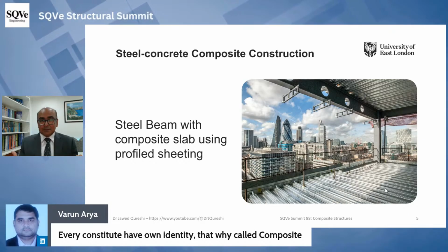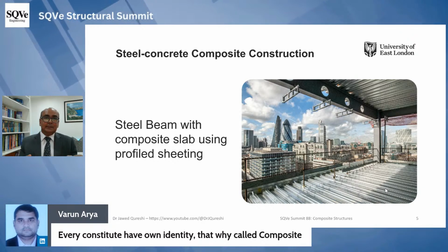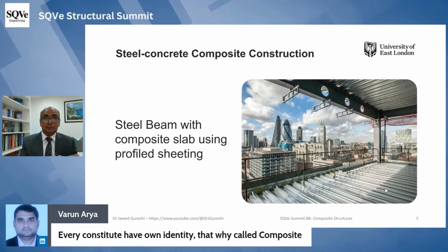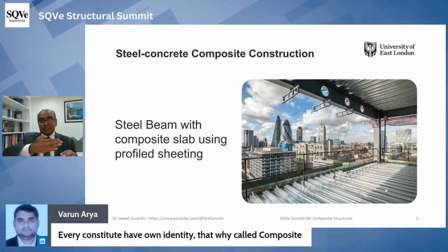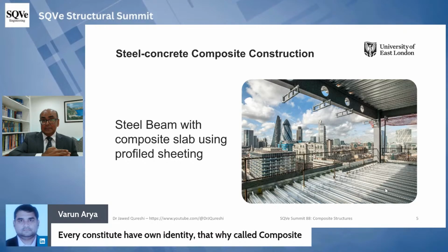Really pretty obvious. Concrete is strong in compression, but really very weak in tension. Tensile strength is almost probably 10% or less. And how about steel? Is steel an ideal material? The answer is steel isn't an ideal material as well. Steel can corrode and steel can buckle as well because the sections are very thin. So when we use them, they can buckle.